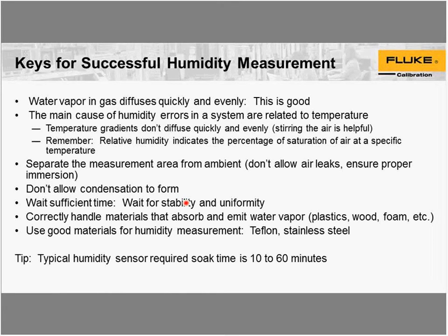Keep an eye on materials that absorb and emit water. Sometimes you have no choice but to include these materials in your measurements, just so that you allow them enough time to stabilize, or at least understand what's happening. And materials good for humidity measurement are typically, think Teflon and stainless steel for the highest levels of humidity measurement.